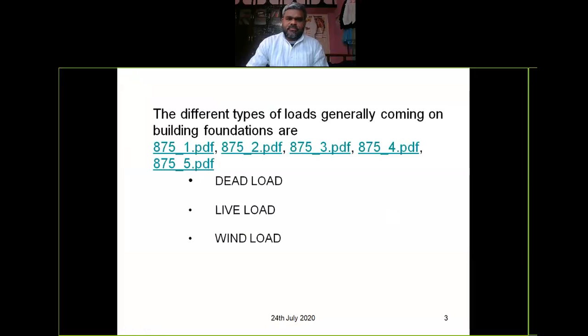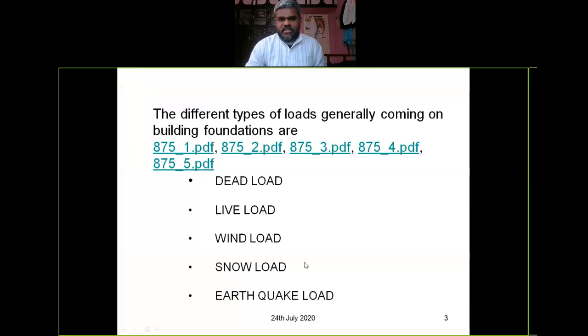There are different types of loads generally coming on building foundations. Those are called dead loads, live loads, wind loads, snow loads, and earthquake loads. Based on these loads, we will design the building, and based on these loads, we will test the soil for bearing capacity, to see whether these loads cumulatively will be taken care of by our soil or not. Based on that, we will construct the foundation.